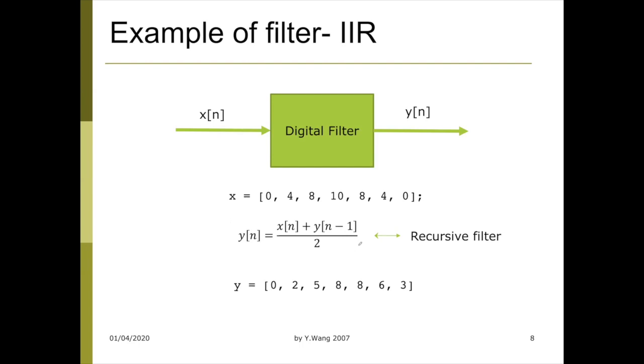This is a different type of filter, which doesn't normally exist in a natural way, like a convolution. We call it an IIR filter. Why is it an IIR filter? IIR stands for infinite impulse response, because you take the output and feed it back into the system. In that way, if you only input an impulse into the system, it might result in an infinite impulse output.